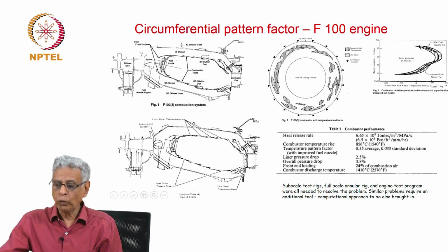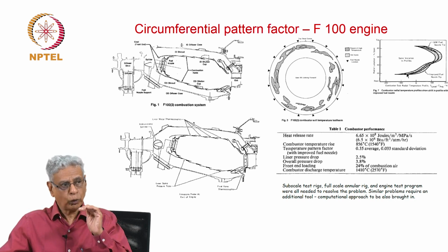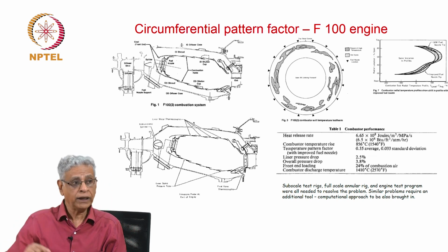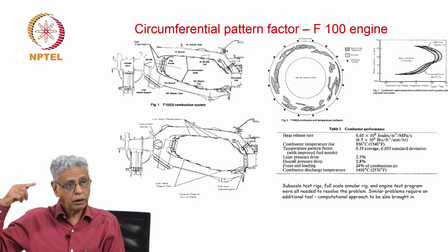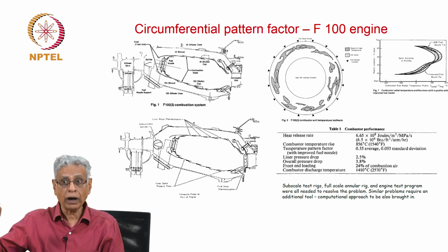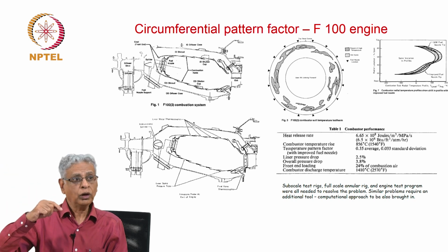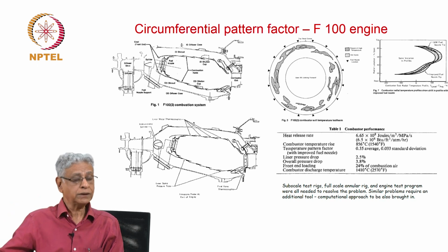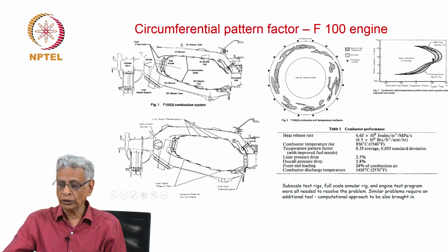not too large at the outer limit as well as the inner limit, because at the turbine root as well as the turbine exit, if the temperatures are too high, it will expand and the blade may extend and brush over the outer surface. It should not happen. Therefore, the tip temperature is limited. The temperature in the root is also to be limited because it is highly stressed because of centrifugal stresses. Therefore, you can allow temperature variation in the middle portion.